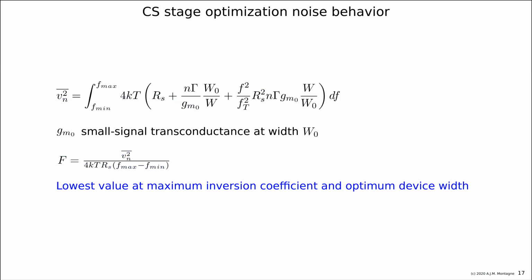Then you are only increasing current, but you don't get GM for it, because the GM versus current curve flattens out. That's what you can see with the Jupyter Notebook tool that we have given you, but also in the graphs that you found in the book and in the presentation.